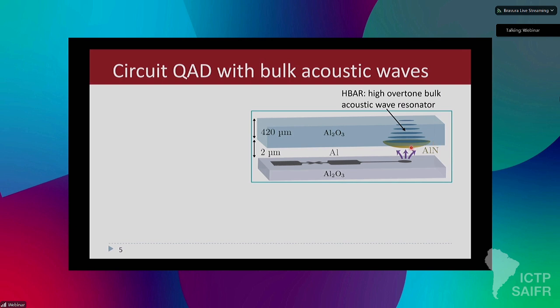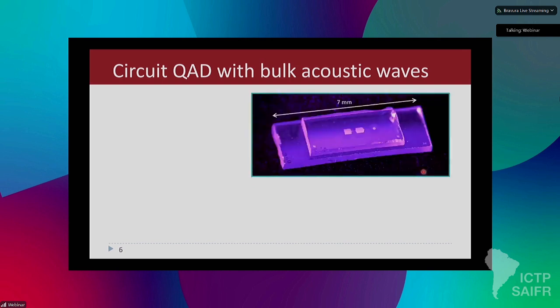All right. And then on our other chip, also made out of sapphire, we pattern our superconducting transmon qubit. Here's the X representing the Josephson junction. You have your two capacitor heads, and this little antenna that sticks out of one of them, indicated here by these purple arrows, is the electric field that once again allows for this piezoelectric interaction.